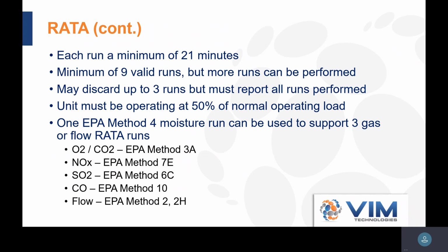I always recommend my clients do at least 10 runs, because you never know when something could go wrong that you don't capture while the test is happening. So if you have an extra run in your back pocket, I know it takes a half hour or 45 minutes more, but you always have an additional run. That way, in case something went wrong with their data system or with your system, you have another run that you can use, and you can toss out the one where something went wrong.